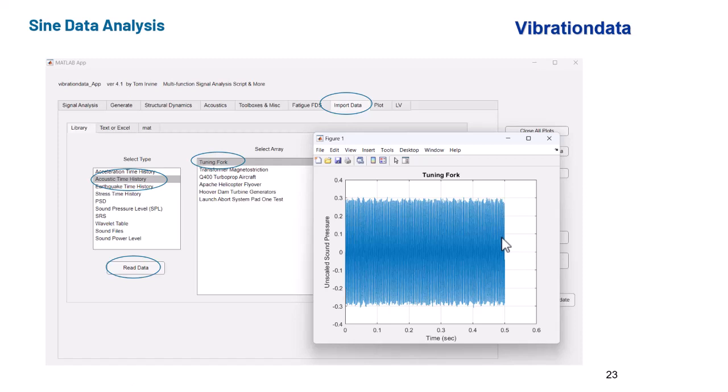So we've got a couple different ways of estimating the frequency. We've already done the count the peaks and divide by time. We can do Fourier transform, except we're not going to do Fourier transform today. That is going to come in a later unit. Well, another method we can use is we can take a textbook sine function and use what I call a hybrid least square curve fit approach. And if we can calibrate that textbook sine function to match the data reasonably well, that's an indirect method to determine the frequency.